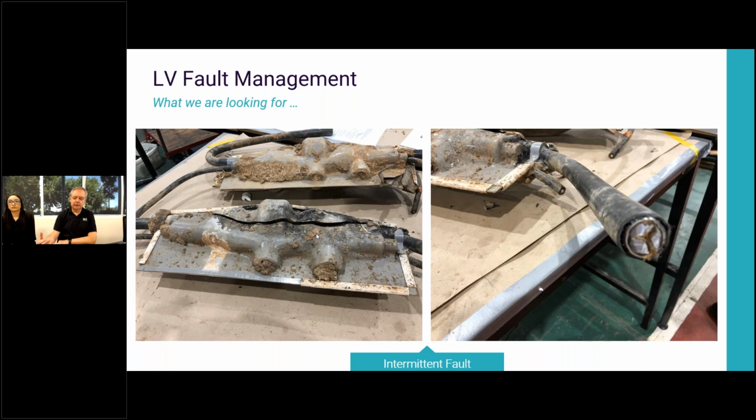So what was typically happening is moisture gets into the cable joint, that causes a flashover, causes the fuse to operate. That drives the moisture out, and when the engineer goes to the substation and replaces the fuse, that holds and stays in there, so it goes straight back in and maintains. Now, due to that, in this particular instance, the company had installed one of our products called an Alvin, which is an auto-reclosing type device, so that will look for the fault and then determine whether it's safe to re-energize the network after a fault, so it reduces the amount of outages.